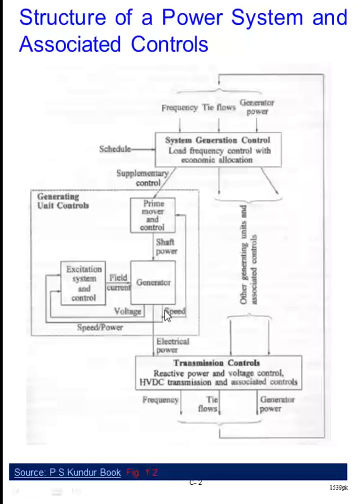So this feedback signal is used for stabilizer design, which feeds the supplementary signal to the excitation system. So if you refer to the block diagram of our power system stabilizer, it is here. Altogether, these two feedback signals are given to the excitation system. One is for the excitation system in the AVR, another is through the power system stabilizer to the AVR section. So we have two feedback signals to the overall excitation system block.